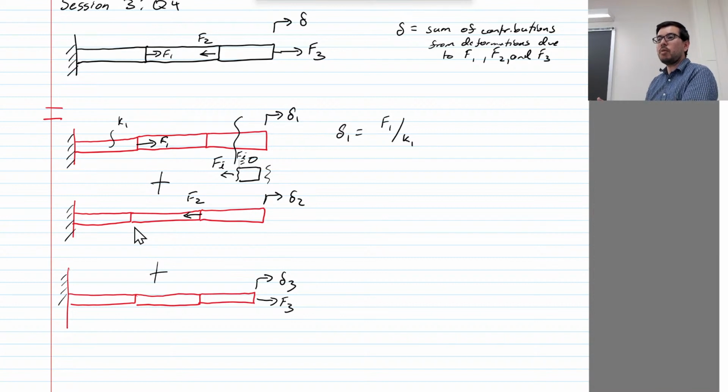It becomes stiffer, right? So that's what happens when you put springs or bars in series or in parallel. We can think of suspensions on cars, suspension bridges. As I use more members to support this load, it's going to become stiffer.